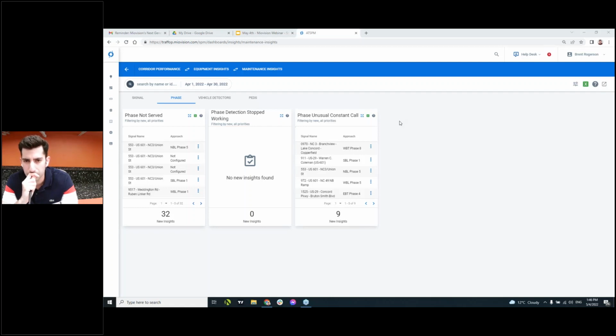So it looks at all of those factors, with the critical ones being just safe operating, like signal flash or power loss, and then less critical being the detector statuses themselves, making sure that at least it's going into fail-safe recalls and operating, and then it can move its way up the list in terms of degrading mode based on that severity.